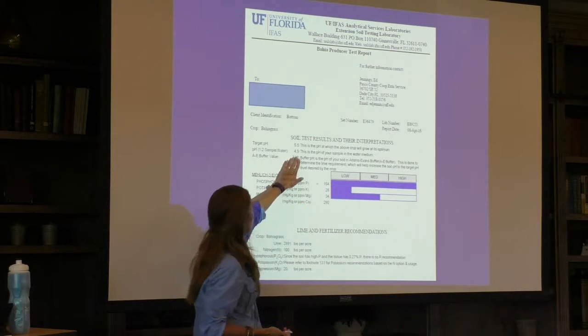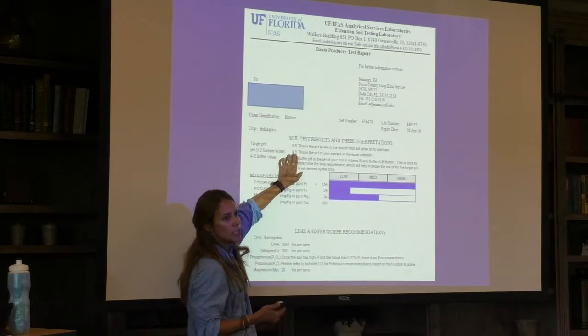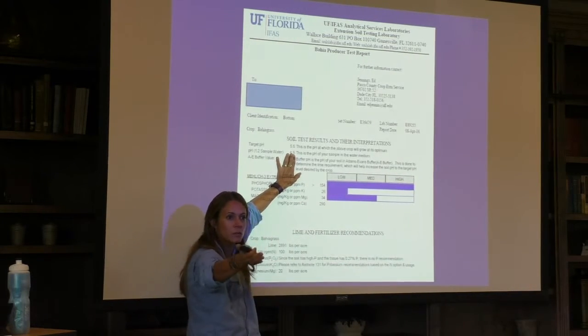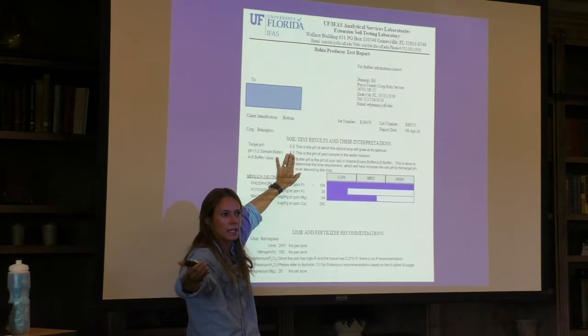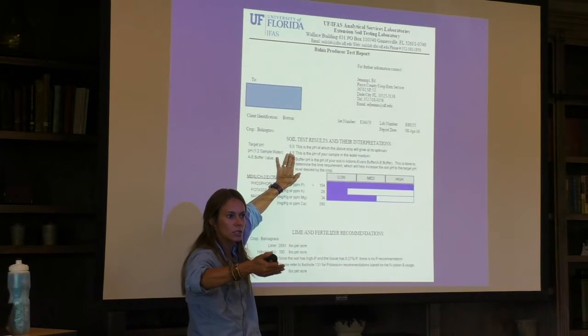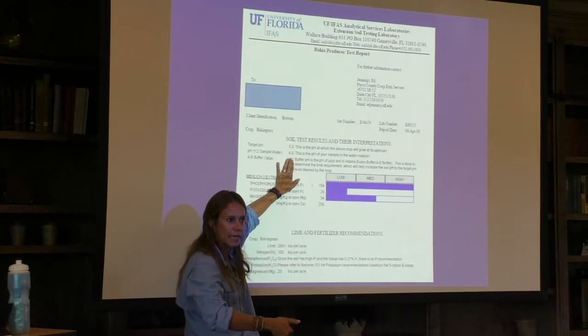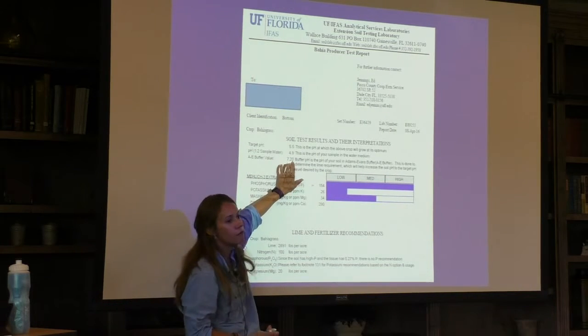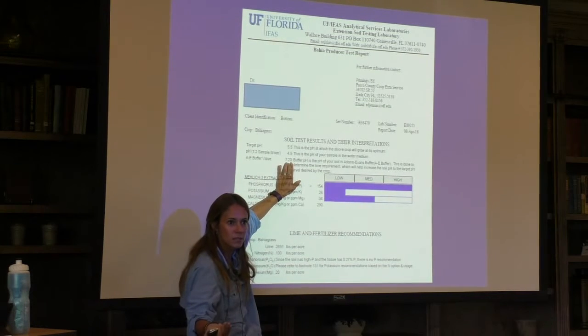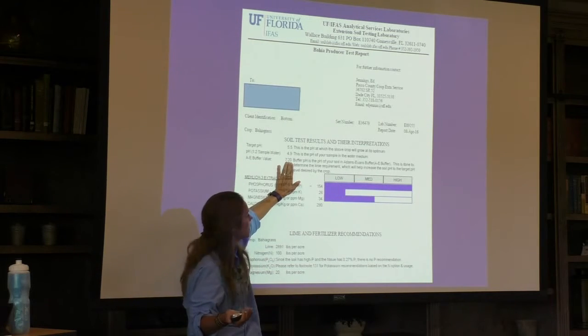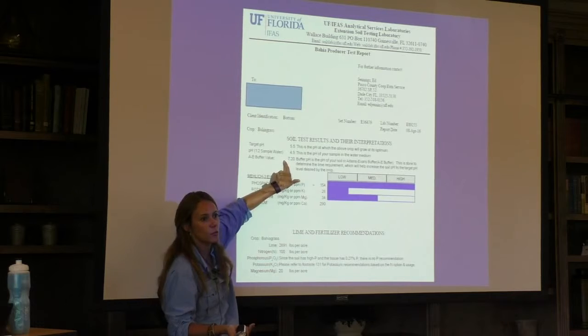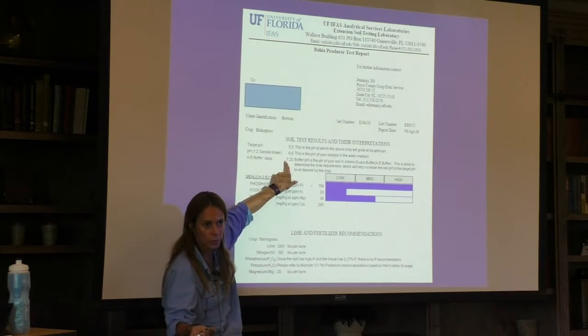This soil had a 4.9, so the soil has a lower pH. After the soil reacts with the solution, the pH of the solution is probably going to be less than 8. Depending on how far from 8 the solution is, that is a direct measurement of buffering capacity. So the lower this number is from 8, the more lime the soil will require.